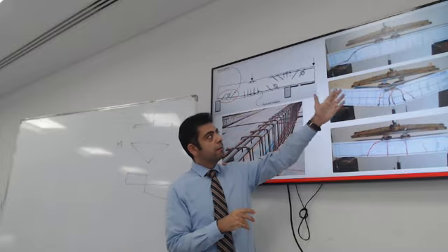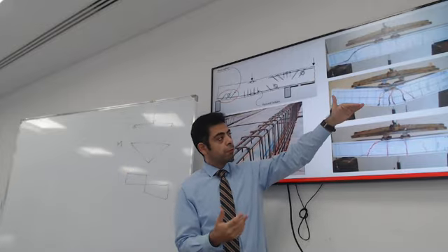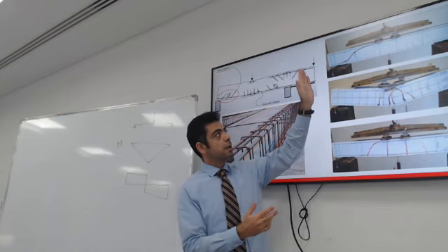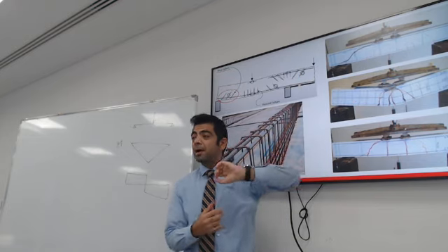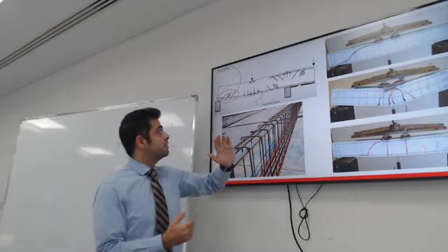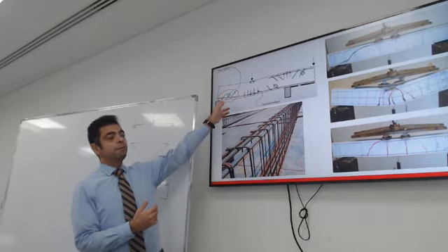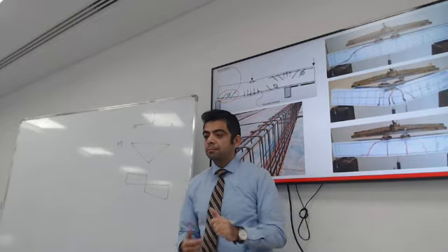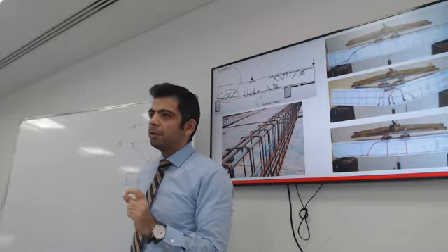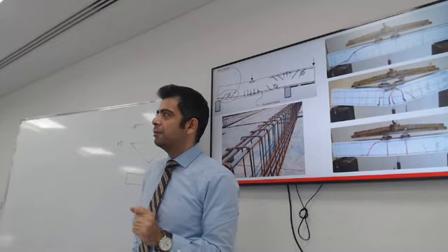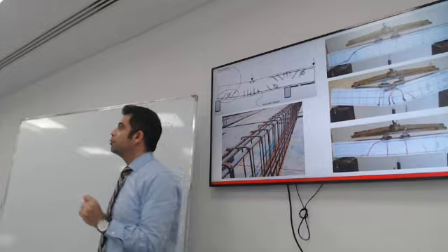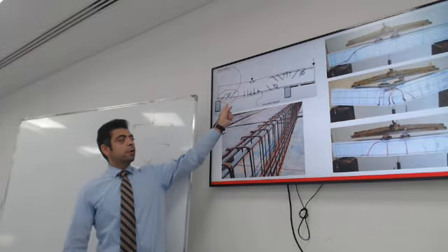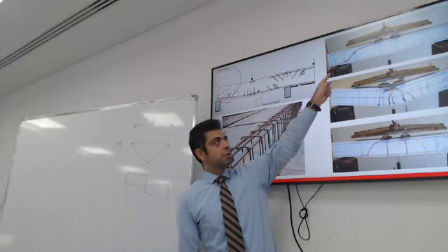So what if the beam is properly reinforced in flexure and properly reinforced in shear? Which is my second question: how do you resist this shear failure in red? How do you resist this crack? I talked about it briefly. I'm curious if you can guess, how do you reinforce the shear crack, the shear failure?